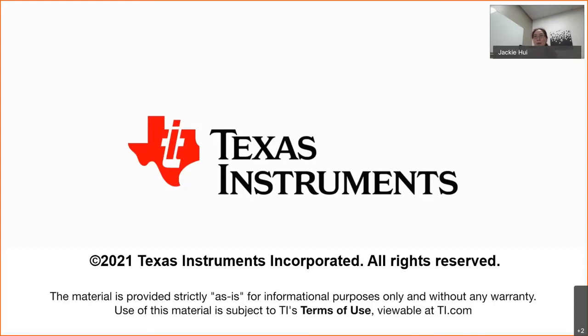Another one is, if your PCB has space, try to put a placeholder for a diode, like a Zener clamp at your switching node, because when you start your initial evaluations, if you have very severe switching noise, you might end up damaging the driver, and you will have a hard time moving forward in your evaluations.